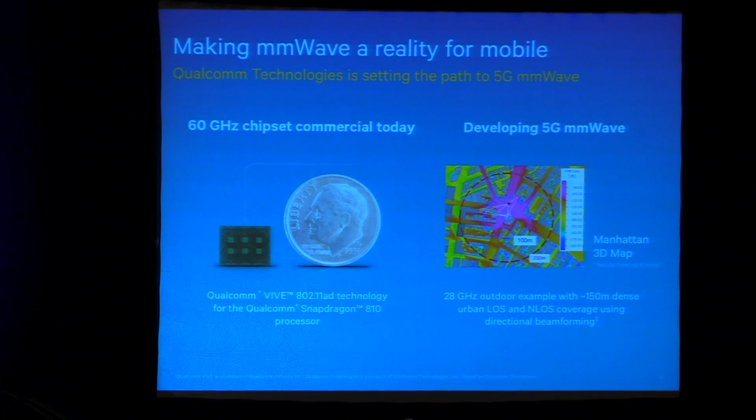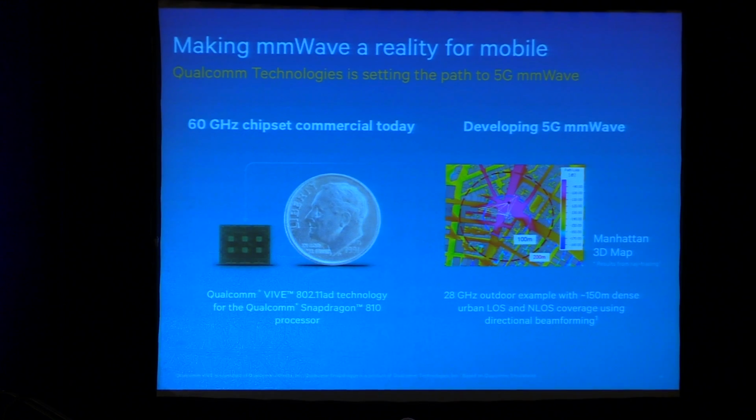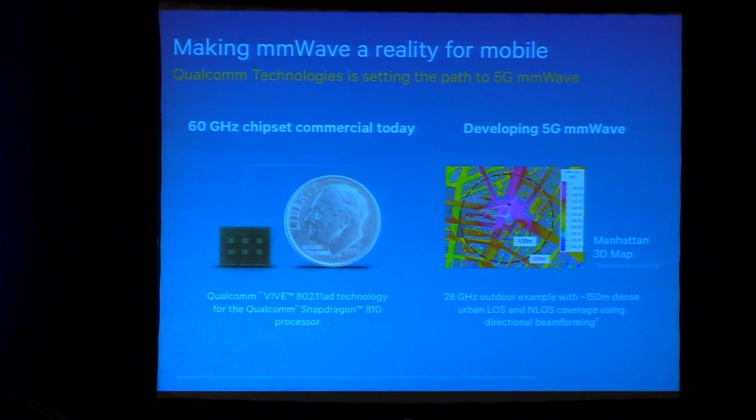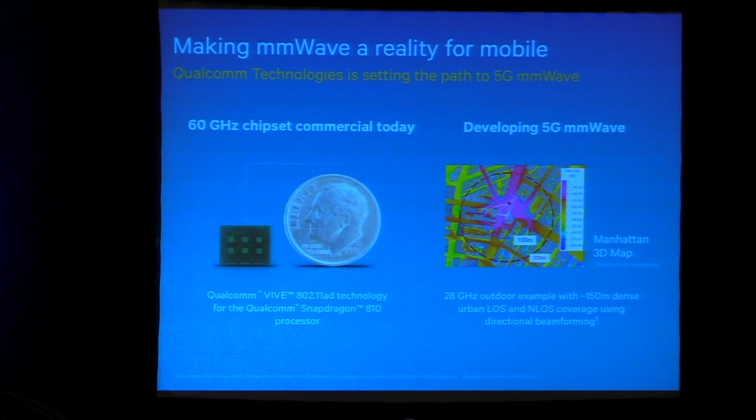Now, the picture on the right is a result from Manhattan, which harkens back to the beginning of Qualcomm when in '89, it was before my time there, but in '89, the first CDMA demonstration was done in Manhattan. And one of the challenges there was to do handoffs when you come around a corner and you see a strong pilot coming into view very quickly and you have to hand off to it. Again, you can see from the colors on here, those same kind of challenges, but now we're at millimeter wave, and you're going to have large numbers of small base stations, but you can get this remarkable performance.